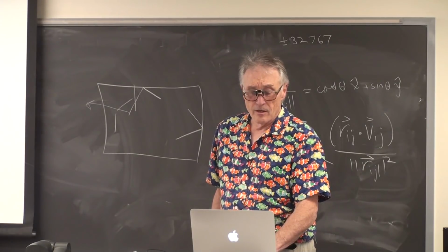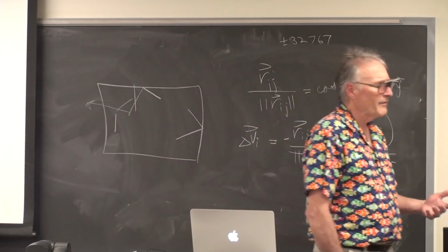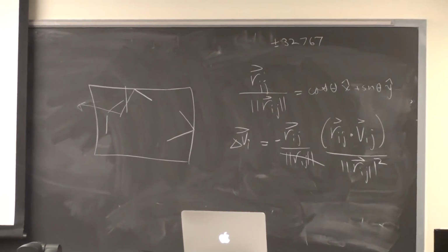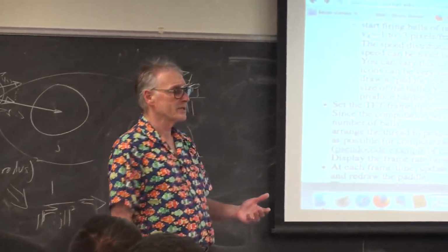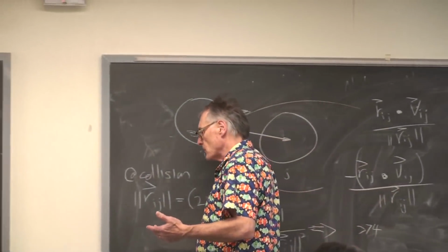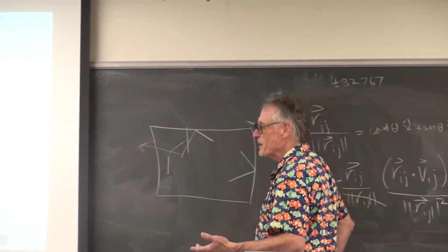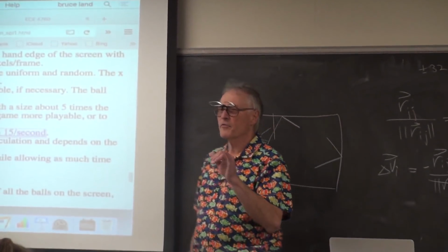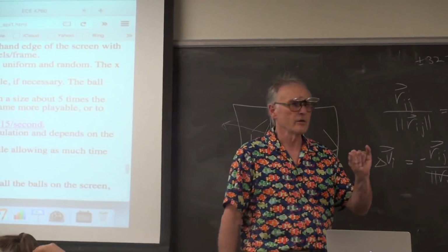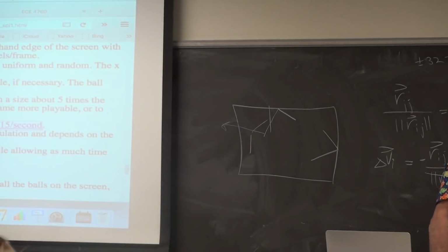But there's a further problem, and that is a typical way to do this would be to have a thread execute every 67 milliseconds, right? 15 frames a second is 67 milliseconds. But since this is not a preemptive system, the thread wait time is merely a lower limit. You can guarantee that the thread will wait at least that long before it executes again.